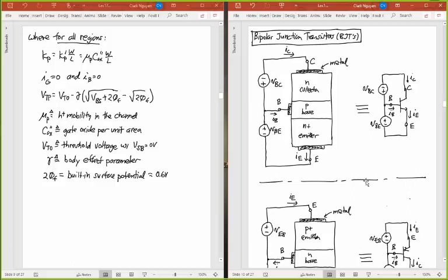your off-chip stuff, of which there's still a lot of applications that use this. And so here's your bipolar transistor. It's basically a couple of PN junctions. If you look at this circuit that I'm showing right now, I effectively have an N piece of silicon connected to a P piece of silicon connected to an N piece of silicon. It says N plus there, and it really is N plus. We're changing the doping concentrations between these for reasons you'll see a little later on.